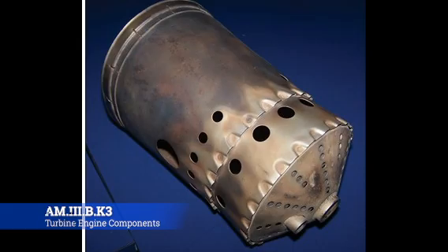Then you need to cool the hot combustion products to a temperature that the turbine inlet guide vane blades can withstand operating under those conditions. In other words, it can light the fire, but if it gets too hot and starts melting the downstream vanes, then that defeats the whole purpose. And then lastly, it needs to deliver the hot gases to the turbine section. It means there needs to be a way out, somewhere to go to spin it up.